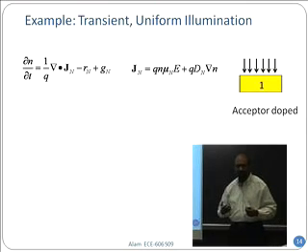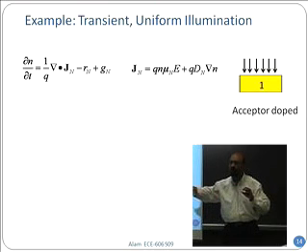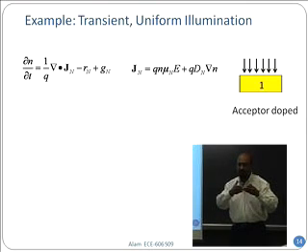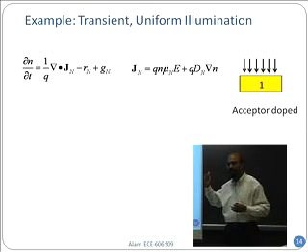What about electric field? Does it have any electric field? Well, I haven't applied any voltage here, and the carrier concentration is uniform. So if the electric field comes in from outside, because the net charge here, and I'll show you in the last equation, is also 0. And as a result, no electric field in this material also.